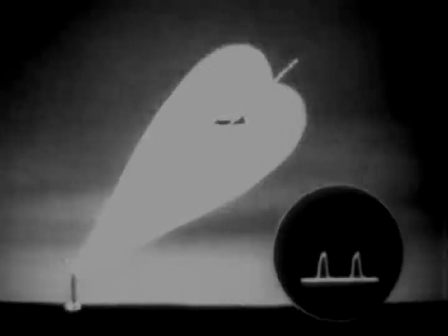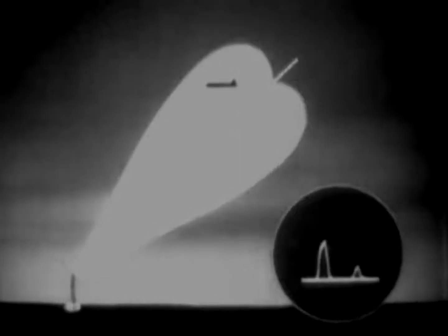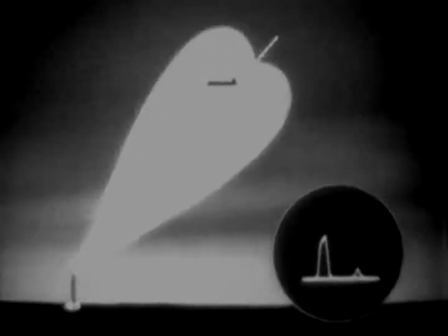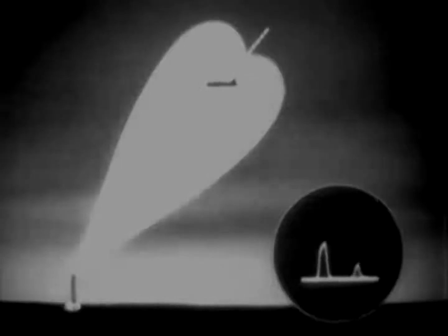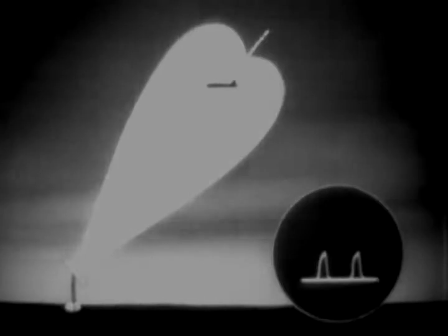is correct. If the plane gains altitude, naturally it'll be in a stronger part of the upper lobe, a weaker part of the lower one. So one pip grows, the other shrinks. By turning your antenna toward the larger pip, elevating it in this case, you again balance the pips and get back on target in elevation.